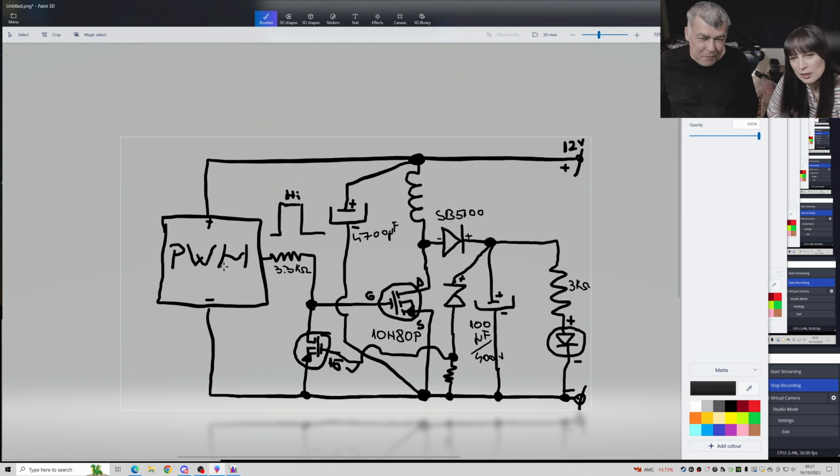But if you put the resistor there, you will still have the 15 volt on the gate? Yes, we are using a higher resistance, like 3-4 kilo ohms. Just a few microamps will be the current going through the resistor, so it will change nothing in this functionality. But when the voltage is lower and will not pass the Zener diode, my gate will be dragged to ground.